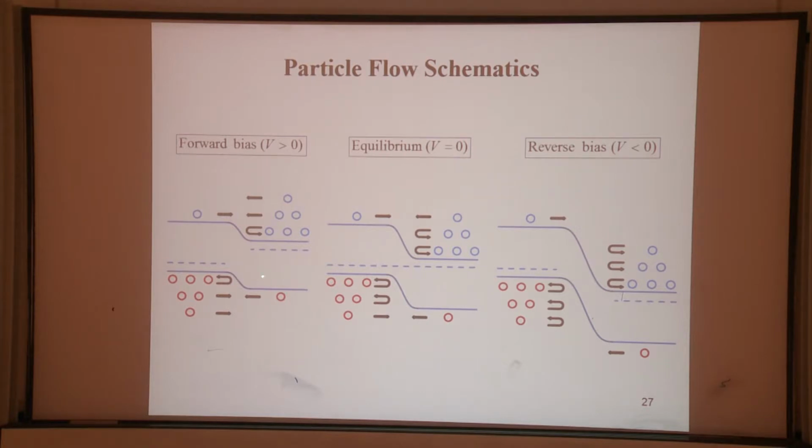In forward bias condition, the current increases with bias, and it induces the diffusion current. Basically, they are diffusion current. In reverse bias, they are normal diffusion current, and the current is very low. This is not the diffusion current. This is called drift current because it is not dependent on the voltage. The amount of current is not dependent on the voltage. It is dependent on how much electron will go to the depletion region and be guided to the other side. All right?